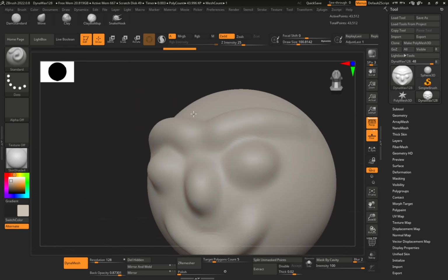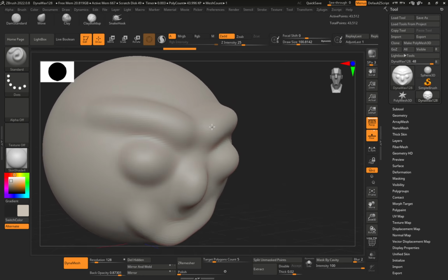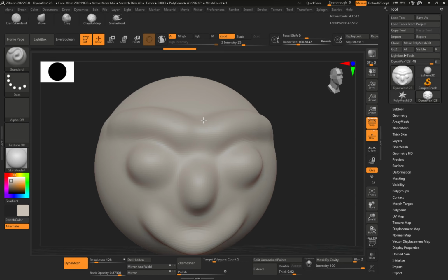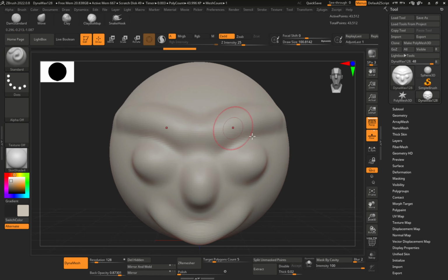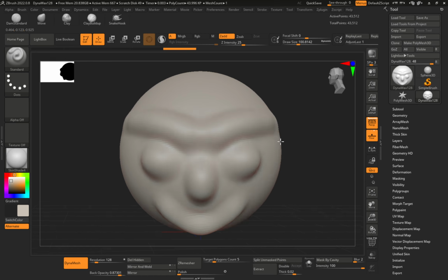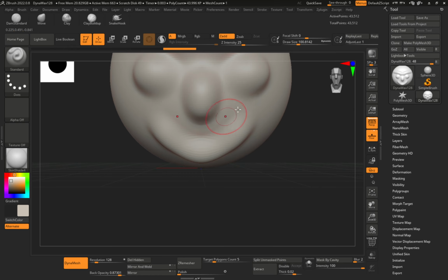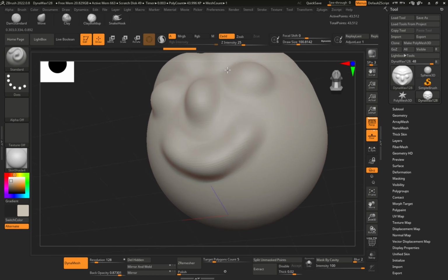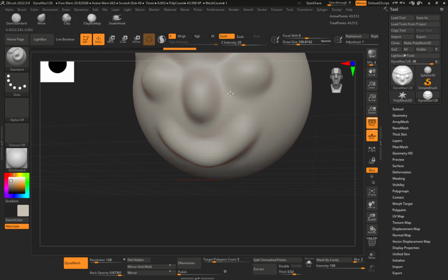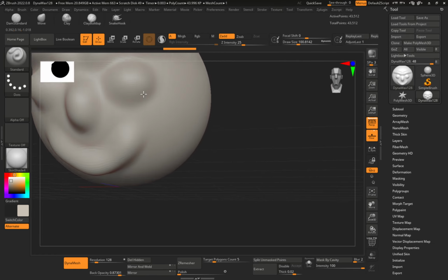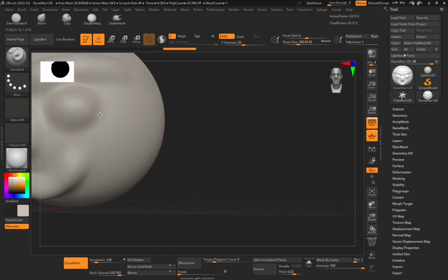All right. And if you want to snap it back to the front view, just hold down Shift while you're rotating, and it will snap to the front, the side, the top, and the bottom view like that. Cool. All right. So that's again, right mouse button down and move. Second is how to drag your object around like that, and that is holding down Alt and then right click and hold. You can drag the camera around so you can see your object.